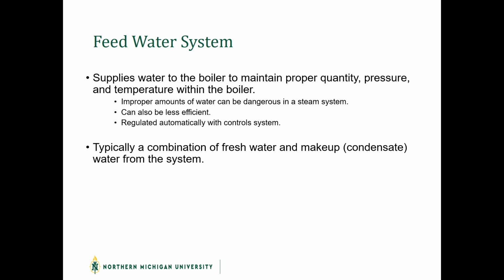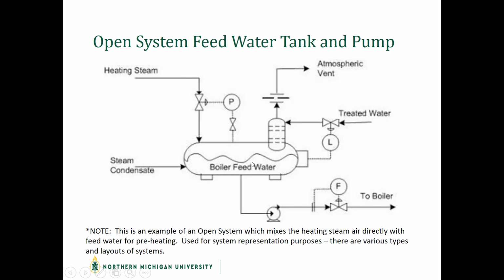Typically what we're doing with feed water is we're combining that condensate tank water with fresh water that's coming back into your facility. And this is just another diagram showing kind of how the boiler feed water comes to be. So you guys can take a look at that as well.